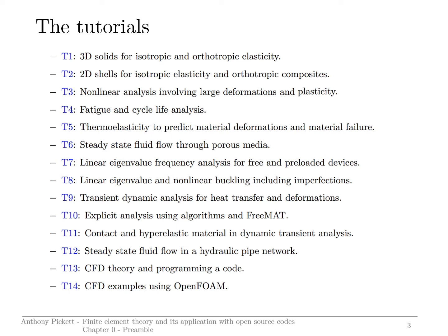In tutorial 10, it investigates explicit finite element methods. The CalculiX code that I use for all of these tutorials, and I will be explaining a little later, does have explicit finite element capabilities, but I was never very successful with these. So this particular tutorial programs a simple spring element in a FreeMAT code, which is similar to MATLAB. And we investigate different effects like different loading, contact, damping, and different time steps used in the explicit algorithm in order to have stable and unstable analysis.